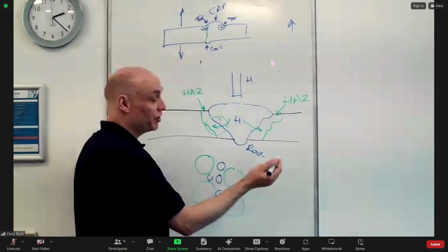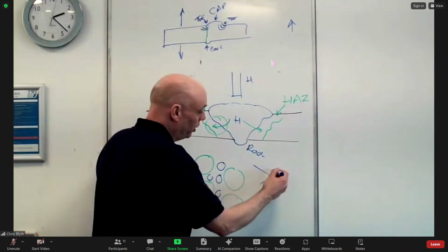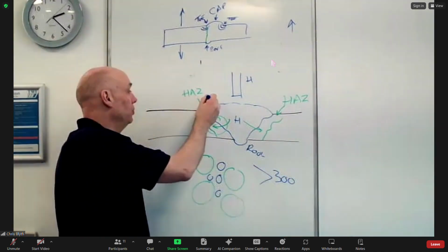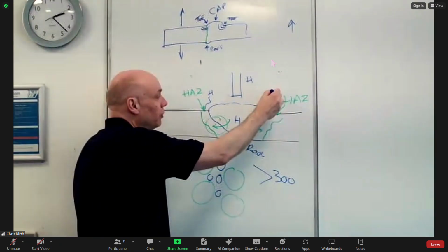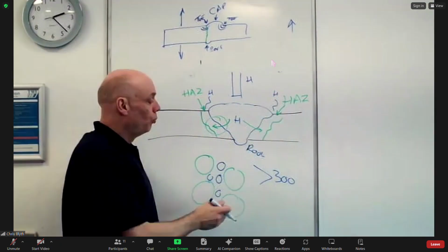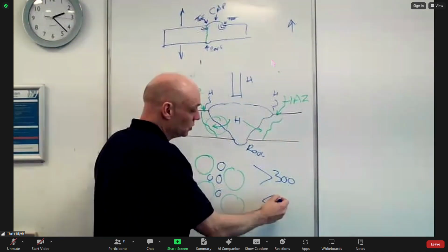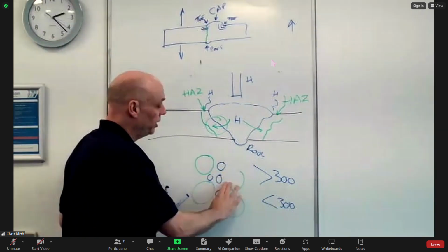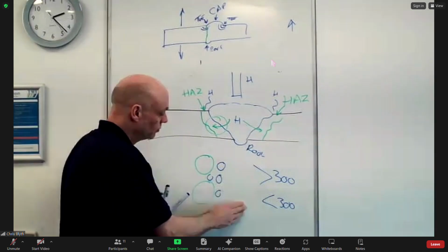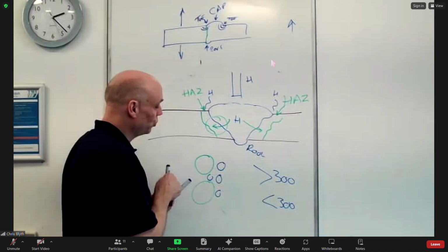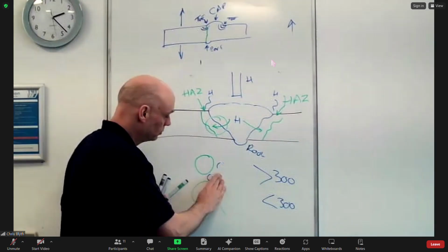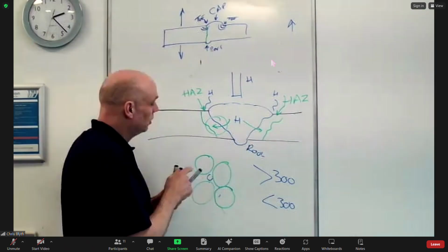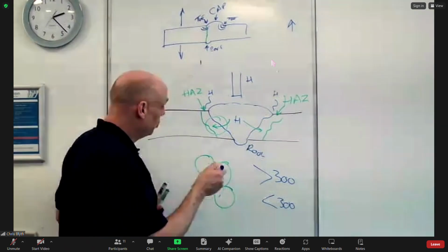Okay. While everything's at an elevated temperature, greater than 300 degrees, okay, hydrogen then can diffuse out of the weld metal. Okay. Well, when we reduce that temperature to less than 300 degrees, okay, what happens? All these atoms of the metal move that much closer together. Okay. When they move up, nice and tight, there's nowhere for the hydrogen to go, it can't escape.